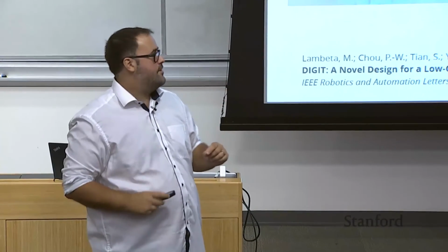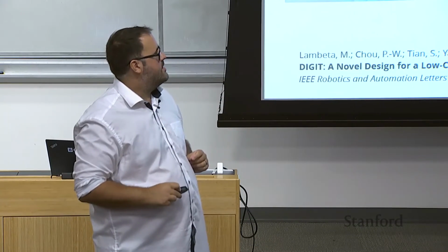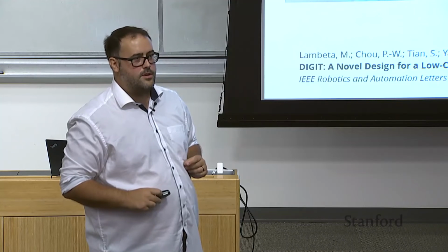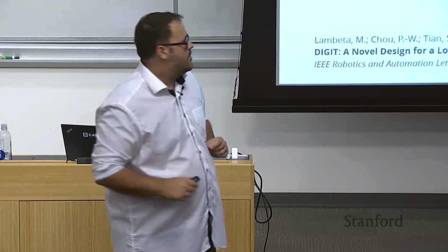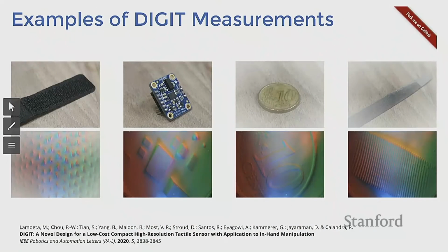The big advantage is the fact that you have unprecedented resolution. A traditional resistive or capacitive type of sensor would probably be a grid of maybe 100, maybe a couple of hundreds pixels in the same space, while here you have 300,000. You can do a resolution which is 3 orders of magnitude higher than other types of technologies, and at a